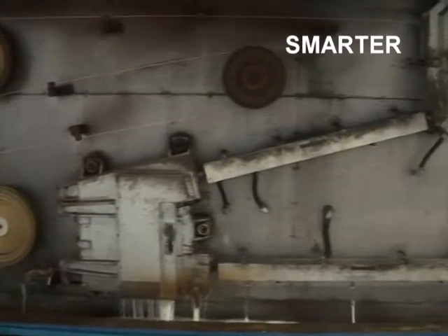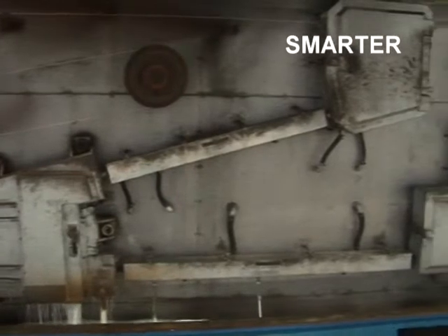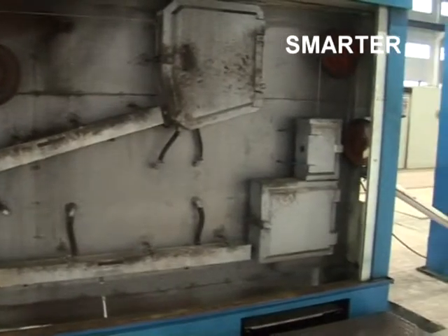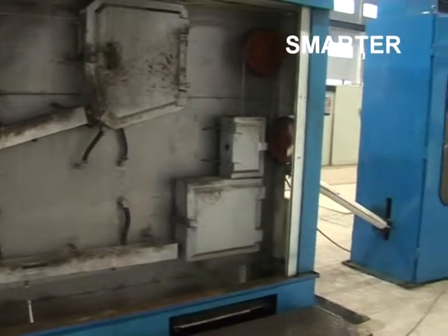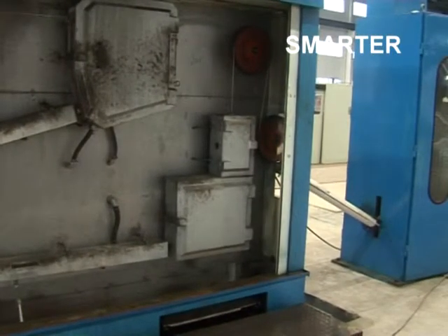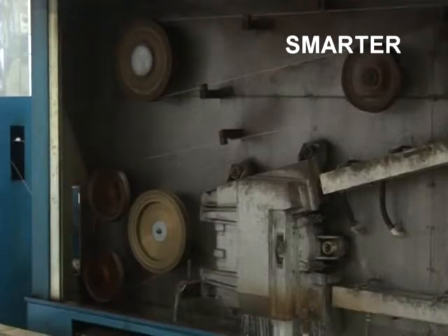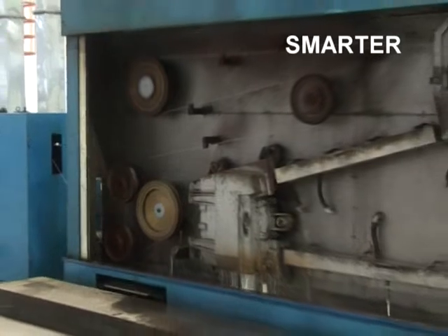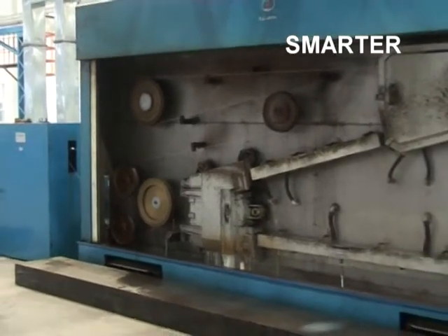The copper wire inlet and outlet are set at the same potential so that the loss of the eddy current can be reduced to the lowest level. Annealing device is a horizontal type with relatively lower height, which is easy for wire threading. The 4 annealing capstans are located in the same plane to avoid wire scraping.